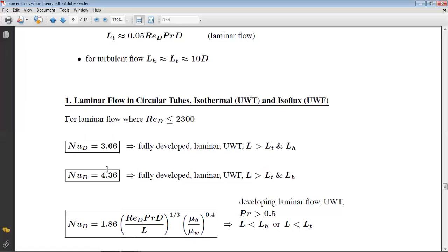It is different for different profiles. For example, for an ellipse, for constant wall temperature, it is 4.439, whereas for constant heat flux, it is 5.331. For a square cross section under constant wall temperature, it is 2.976, and for constant heat flux, it is 3.60.